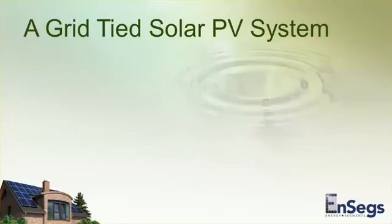Let's start by looking at a grid-tied system. A grid-tied system is less complex than an off-grid one and is more commonly seen, since it has fewer components and is generally less expensive. For example, there are usually no batteries in grid-tied systems. In essence, the grid is your battery.